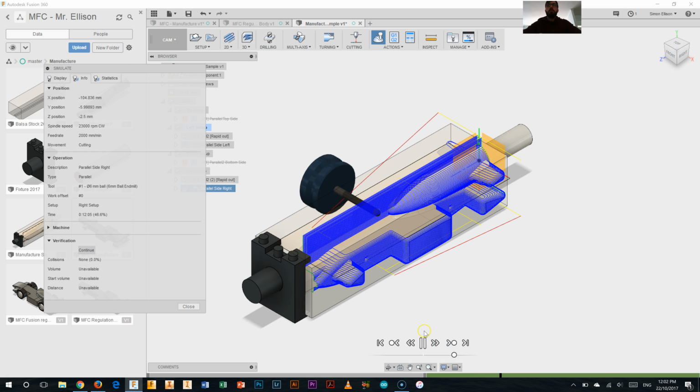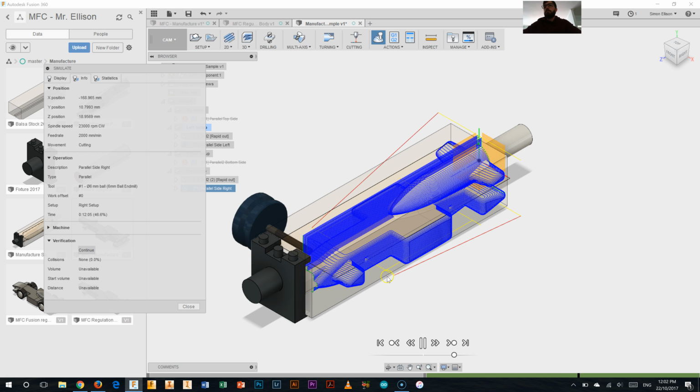So overall, it will take a little while to machine your entire car, to do all the different parts of it. But if we were to change settings and perhaps add in a top-down or a bottom-up machining, as well as reducing perhaps the distance that our cut takes, so if the step over at the moment is 0.6 of a millimeter, if we would reduce that further, it would again take even longer because it's going to take more passes over the same area.